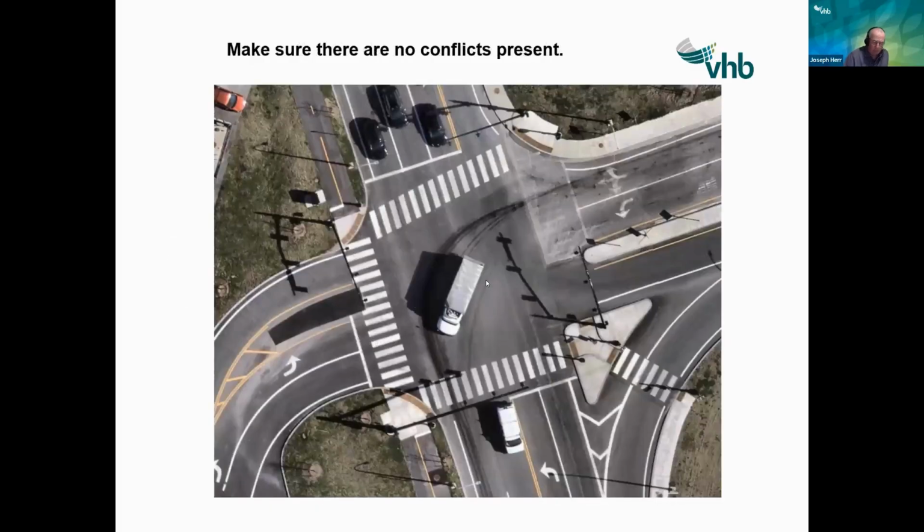And last, and probably the most important, is make sure there are no conflicts present. What do I mean by conflicts? Well, you got vehicle conflicts, green against green, green against yellow, green against walks, but you also have conflicts between the buttons and the displays.